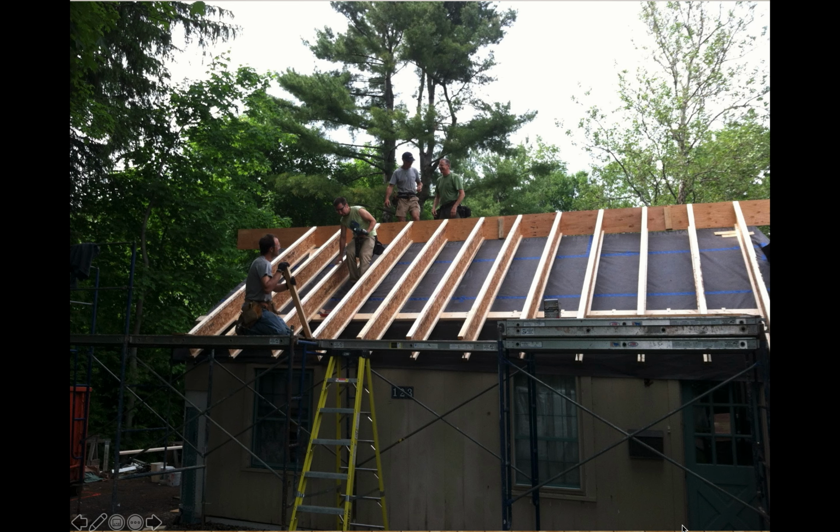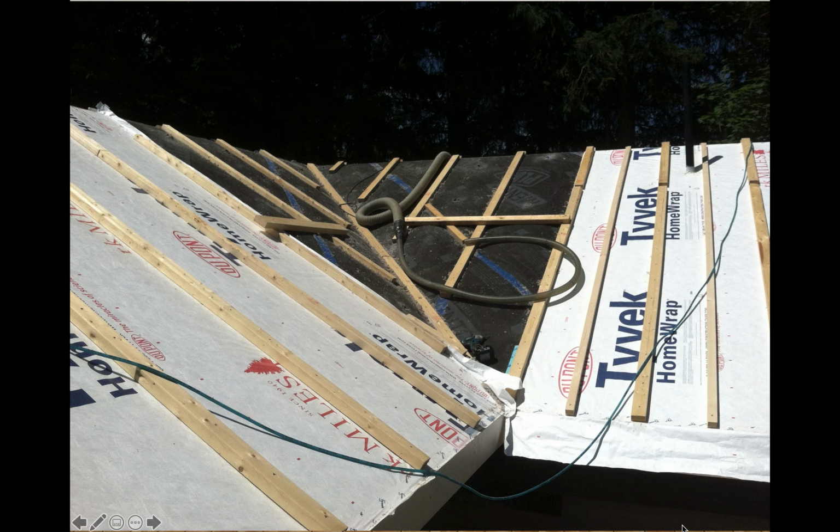In this case, I wanted to avoid foam, one, because it's more harmful to the environment, and two, because it's a little bit more expensive, and this approach was actually less expensive. So we filled the over roof with insulation, which was challenging in the valleys. And so a lesson here was about how to plan for dense packing cellulose.